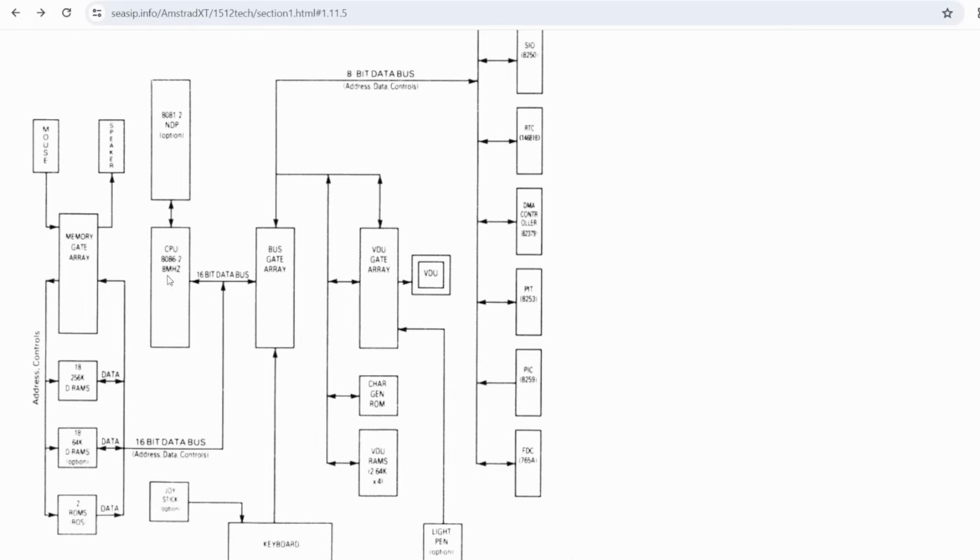So we'd need 2 CPU cycles at 8 megahertz for every 8-bit data bus cycle. And so that's why we have this 120 pixel per second difference instead of what I'd expect, which would be closer to 60 pixels per second. So we've explained exactly why we can't get a difference of just one CPU cycle, but it's always 2 CPU cycles at a time. It's because of this limiting factor, this 8-bit data bus running at 4 megahertz.